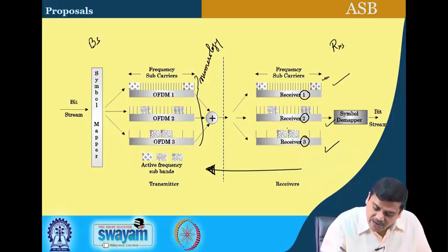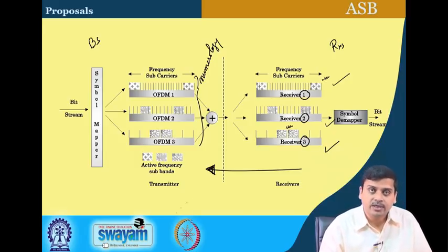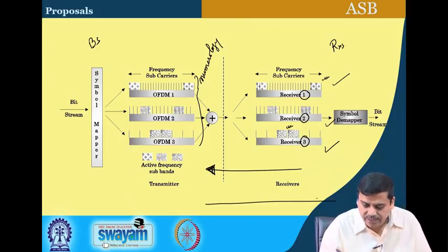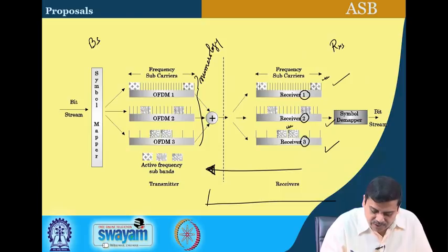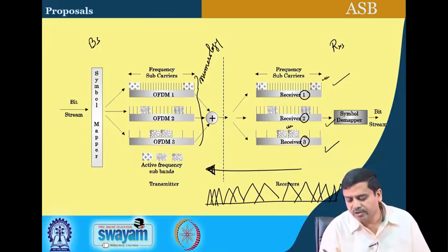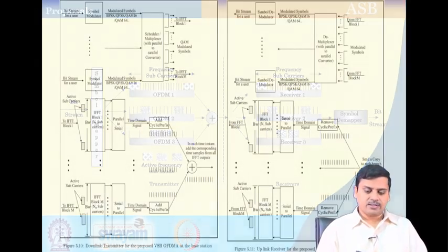This transmitter would activate only this set of subcarriers. So, when the signal arrives at the base station, one would find that corresponding to this there are some narrow band subcarriers, then there will be a little bit wider band subcarriers, and there will be even wider band subcarriers next to each other. So, this way one can have a mixed numerology architecture.